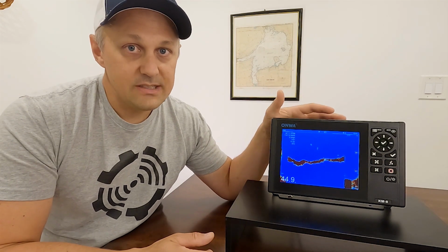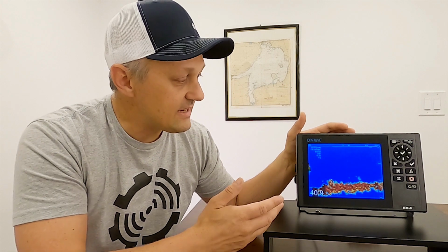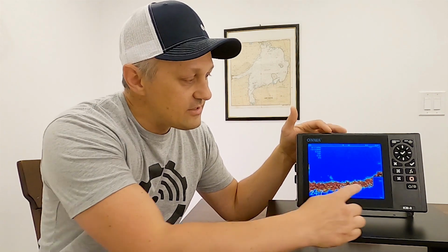In my opinion, sonar is definitely something anybody who's boating needs. Whether you're fishing, sailing, or just on a pleasure boat, it's always good to know the true depth below the hull of the boat and not rely on the charts itself in order to give you that information. The unit's also able to tell you the bottom density. So if you're going into an anchorage and want to determine if you have mud or rock on the bottom, you're able to do that based on the color that you're seeing on the sonar screen.